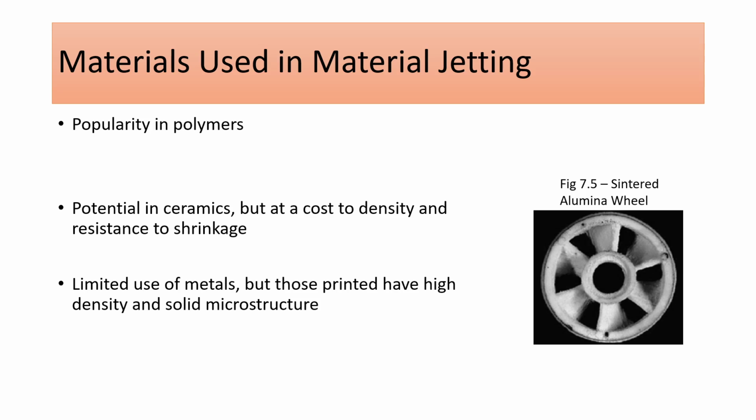Now, in material jetting, polymers are king. Polymers such as the aforementioned photopolymer and other waxes remain the only materials in the material jetting process that are commercially available. In large part, this is due to the viscosity of the liquid materials. Commonly, the maximum printable viscosity is around 20 to 40 centipoise, which is an equivalent unit to millipascal seconds. However, high viscosity liquids can negatively affect droplet formation and clog the nozzles. A solution to lower viscosity would be to simply heat the liquid, but this can negatively affect the machine components if heated too high.